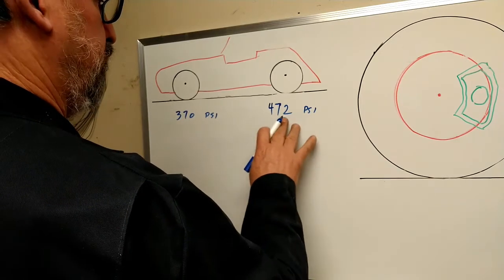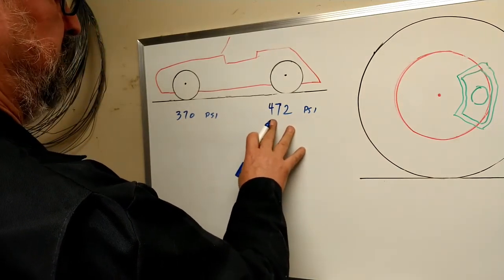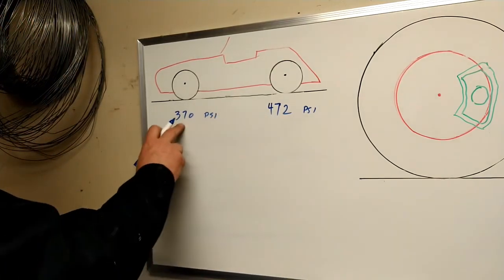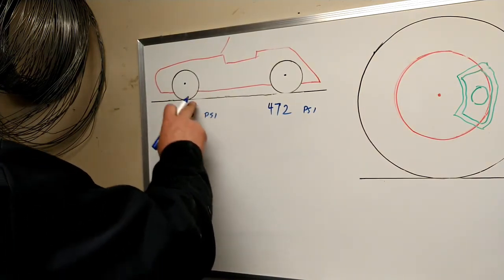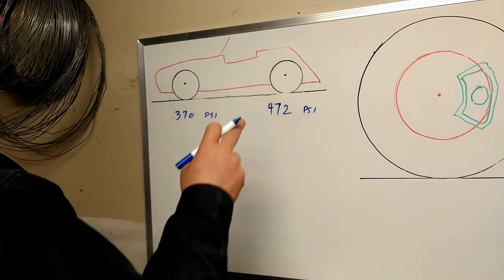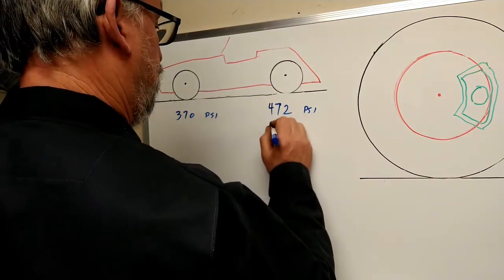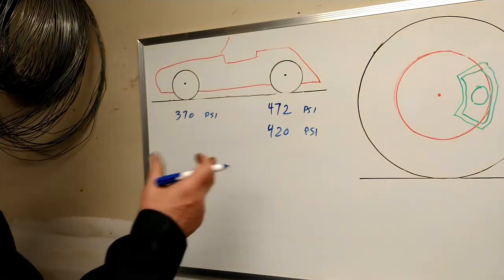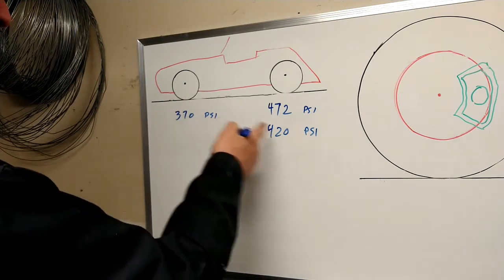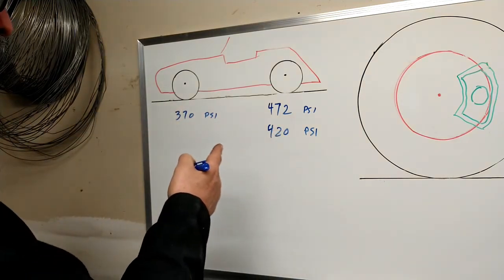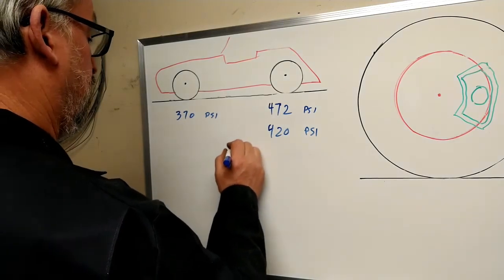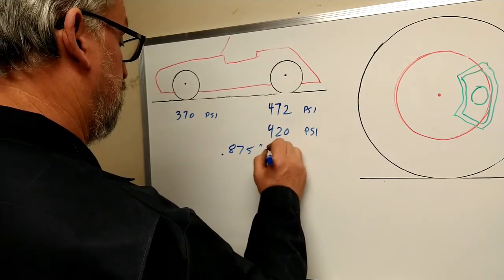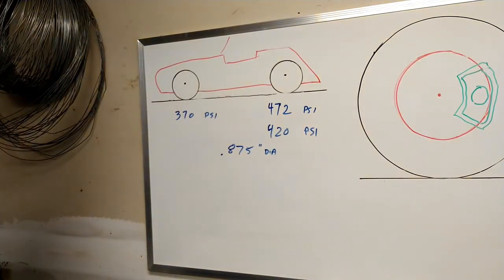back. So I'd like to reduce this by maybe 10%, which takes 50, so maybe 420 psi maximum that I want in the backs if I have 370 in the front. So that means that the fronts will be locking up, the backs will still be turning. Given that we are at 420 psi here, that's what we want in 370 there. We're close enough that I picked the same master cylinder sizes. I picked 7/8 master cylinders, so 0.875 inches diameter for the master cylinders.